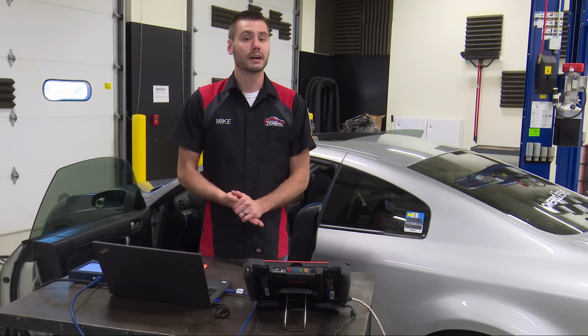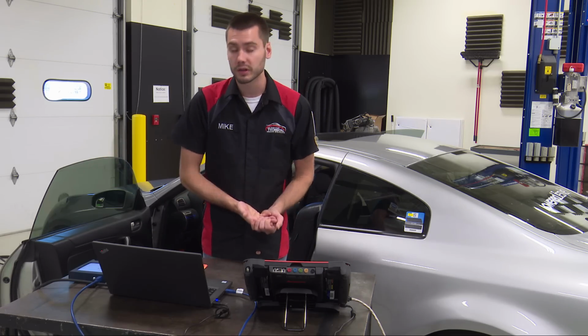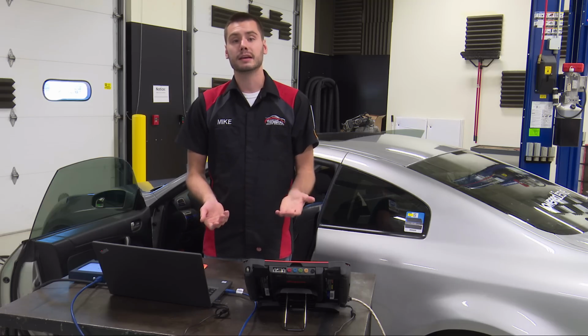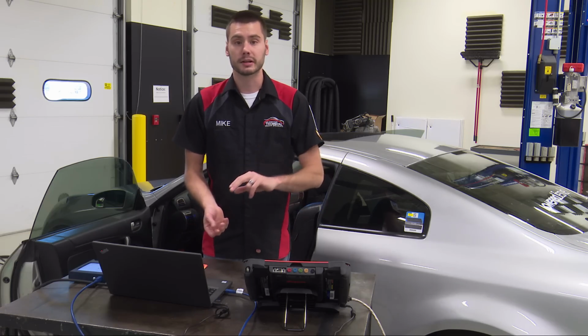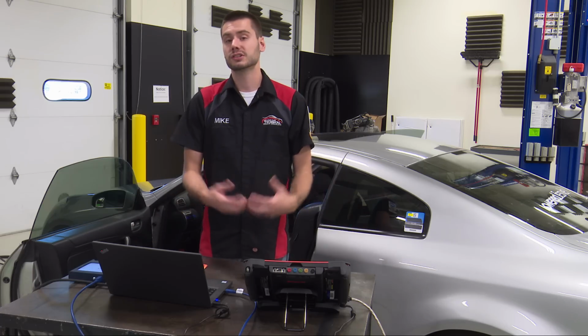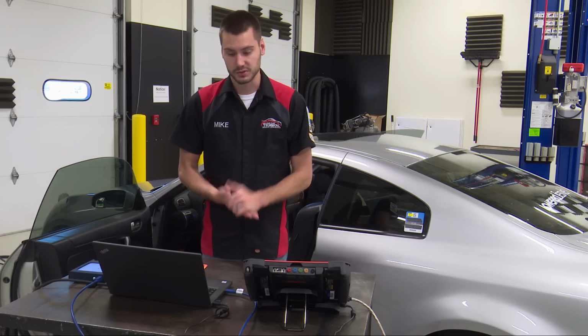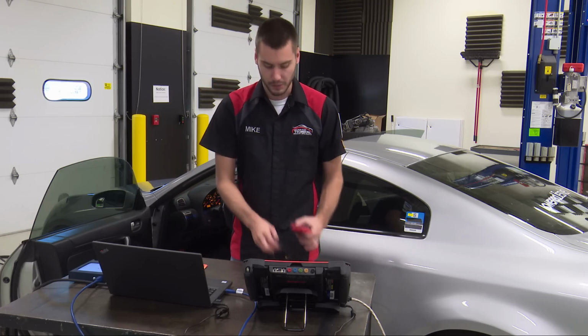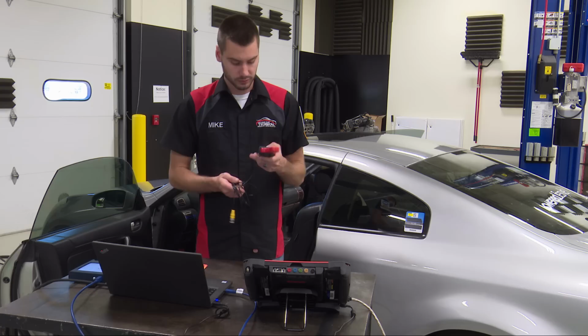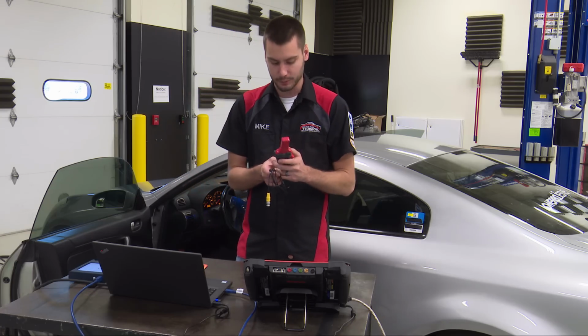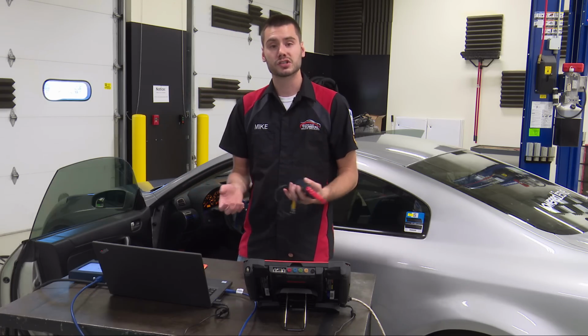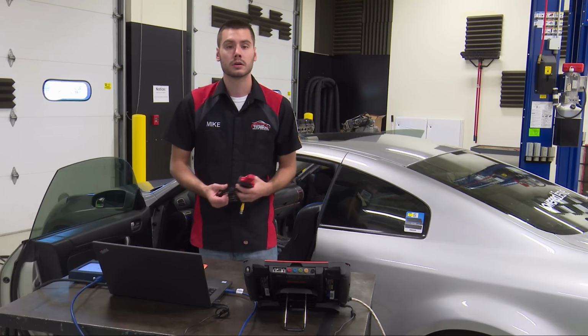Power windows really aren't any different. Yeah, our control on here is different. Yeah, they are bidirectional or they swap polarity to move up or down, but they're still an electric motor and we can still scope amperage on them. So I have the scope out. I have 2 amp clamps out. Let's start them off on the 20 amp range. And what we're going to do is scope each window and see what happens.